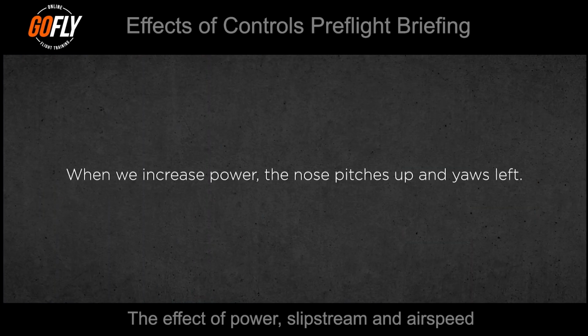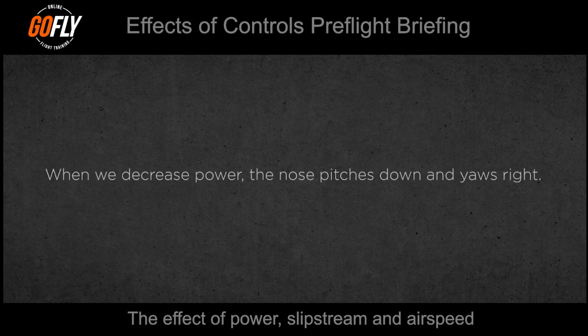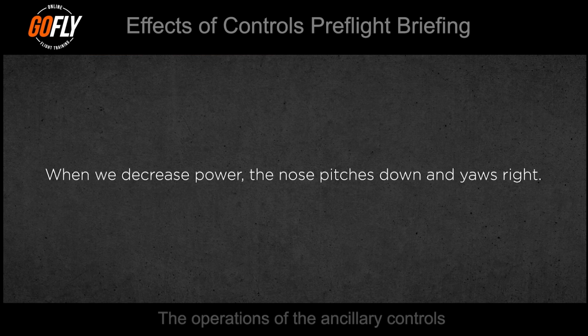If we add these effects together, we can see with a clockwise rotating propeller, when we increase power, the nose pitches up and yaws left. And when we decrease power, the nose pitches down and yaws right.